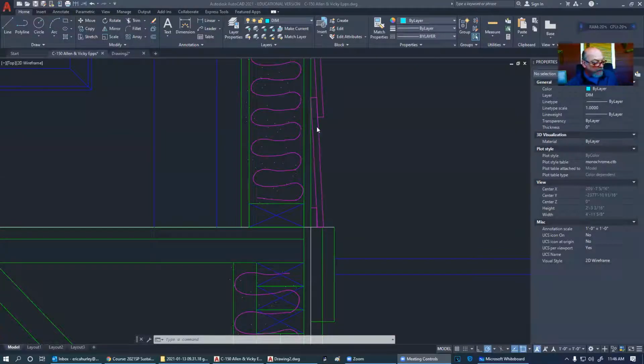You've got a 1/2 inch sheetrock on the inside. A stud is 1.5 inches tall by 3.5 wide. And then you've got 7/16 sheathing on the outside. And generally, most of our Hardie board and fiber cement siding and stuff like that is going to be about 1/4 of an inch thick, somewhere in that neighborhood, maybe a little bit more. I think it's actually about 5/16, something like that. You don't have to get super picky on it, but I just want you to understand how the makeup of the wall goes.